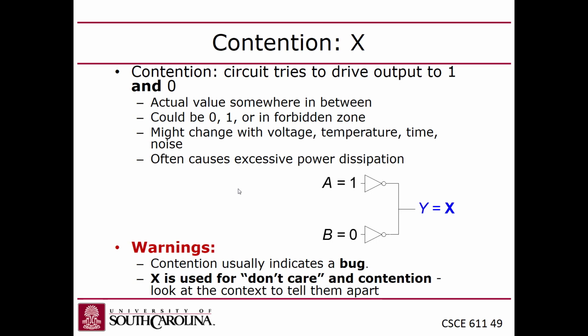You guys with me? When I say drive, I mean set or output. In other words, you've got multiple gate outputs connected to the same wire, right? You can't have that. You don't want to have that unless there are tri-states on there to protect against this condition of double driving. Does that make sense to everyone?